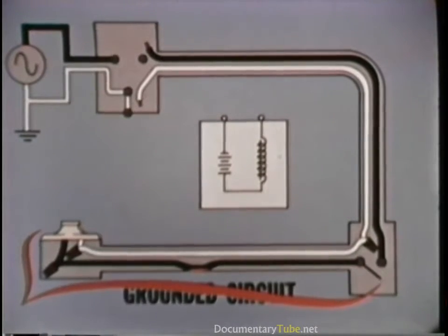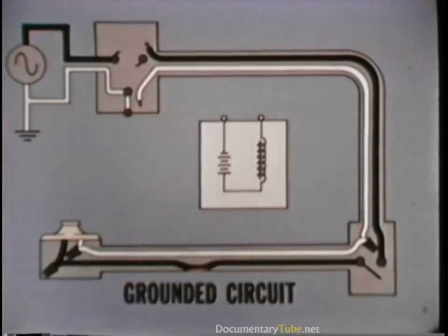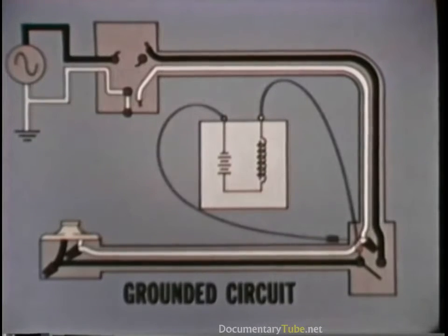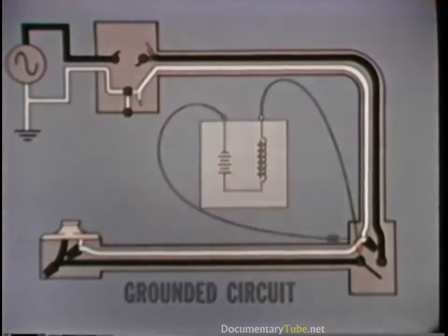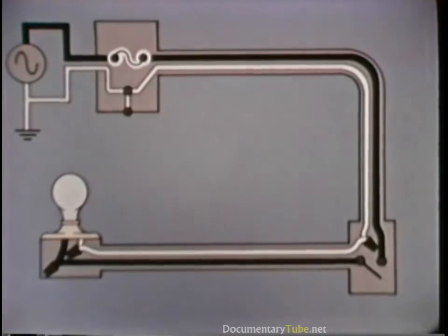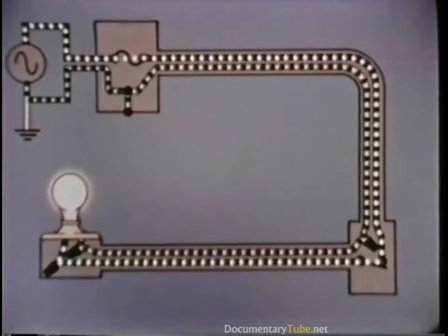Since this is the last section, the testing is complete. In a longer circuit, the diagnosis would be confirmed by checking the next connection. The ground is removed, and the circuit is retested at the trouble point, and all connections are restored. The light and fuse are replaced, and when the switch is turned on, the circuit is back in service.